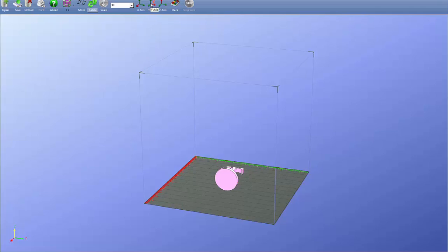Let's go over the general process used to print a 3D part. We're not going to talk about the specific machines, but go over a general overview of the process. The first step in printing a 3D part is to have an electronic part file that you want to print. This is an STL file type. This is typically created in a CAD design software package like SolidWorks, Inventor, or Creo. It can also be created in a creative design software package like Mudbox, 3ds Max, or Rhino.